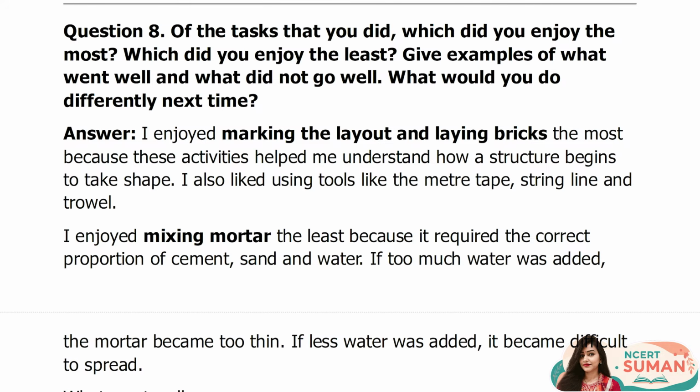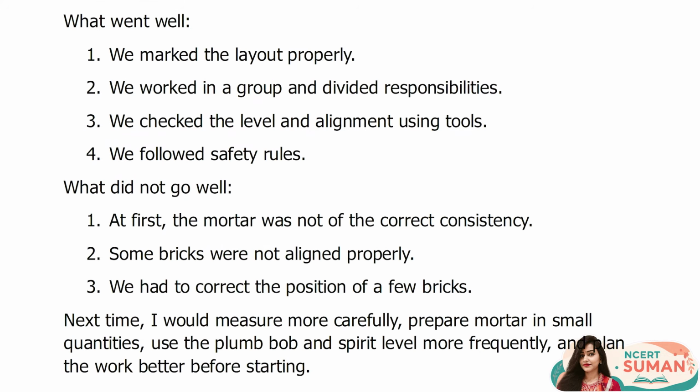I enjoyed mixing mortar the least because it required the correct proportion of cement, sand, and water. If too much water was added, the mortar became too thin. If less water was added, it became difficult to spread. What went well? 1. We marked the layout properly. 2. We worked in a group and divided responsibilities. 3. We checked the level and alignment using tools. 4. We followed safety rules.